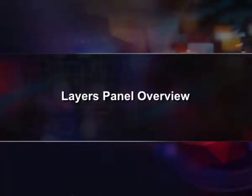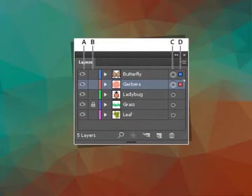Layers panel overview. We can use the Layers panel window to list, organize and edit the objects in a document. By default, every new document contains one layer and each object you create is listed under that layer. However, you can create new layers and rearrange items to best suit your needs. A. Visibility column. B. Edit column. C. Target column. D. Selection column.